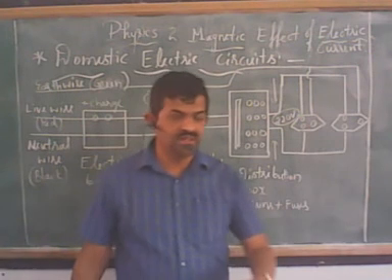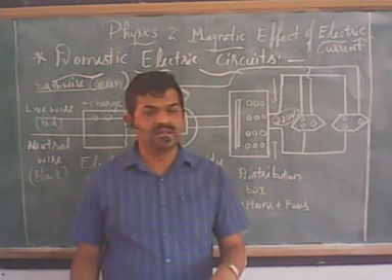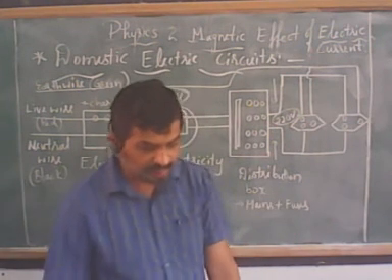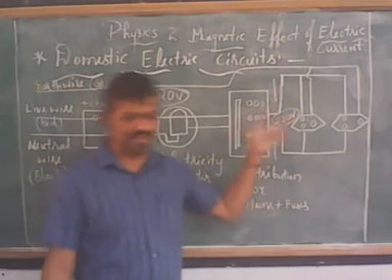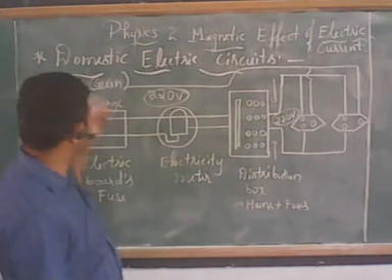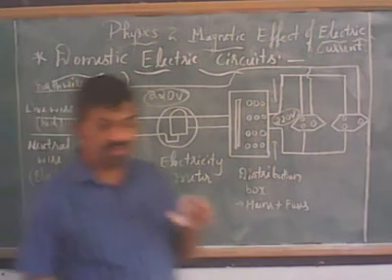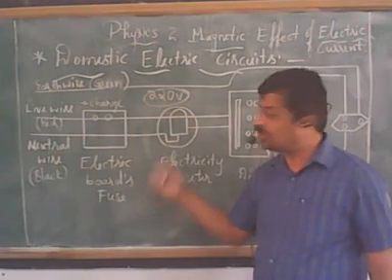You have seen we dig a pit near the house and fill it with sand. Correct? We fill sand and charcoal. We draw the wire. Correct? So we insert the long earth wire. The earth wire is normally green in color. So why the coloring for the 3 wires? To identify. Identification is important because if there is any problem in the circuit, the electrician should repair it.